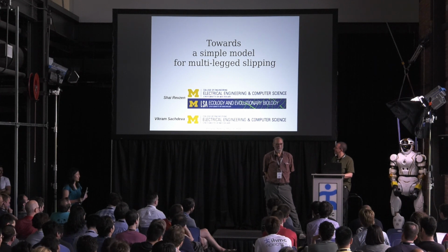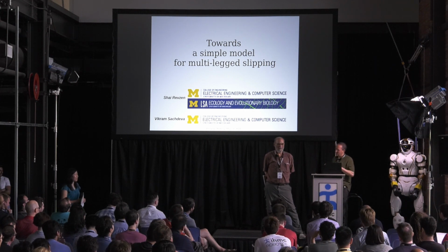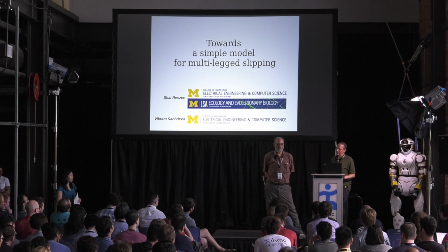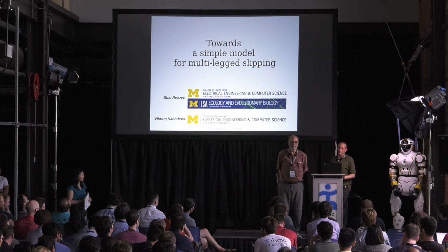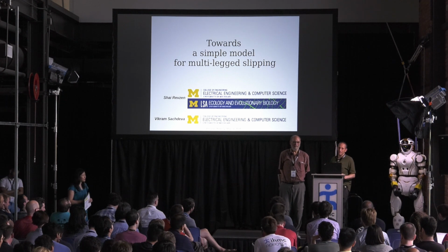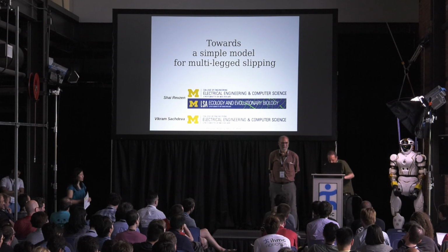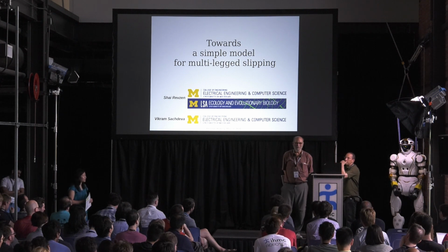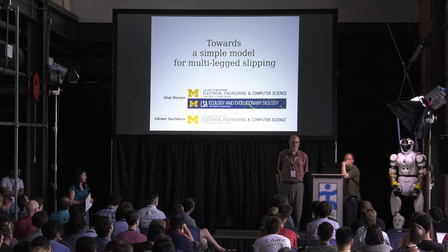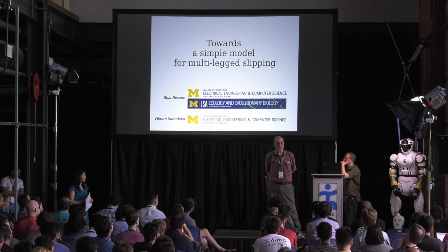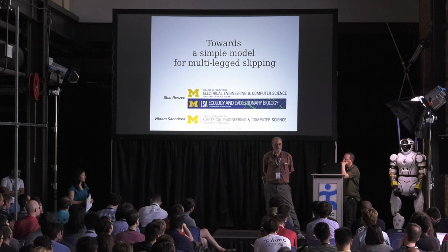All those extra degrees of freedom, when you control your robot, you have to figure out what to do with them because they're there. And those extra degrees of freedom can make your robot fail various ways. Like if you don't pay attention to them, the right leg will trip on the left leg, or it will trip on the ground, or there'll be the sudden ground reaction force and it will hop in the air. So there are lots of ways you can fail besides simple balance failures.